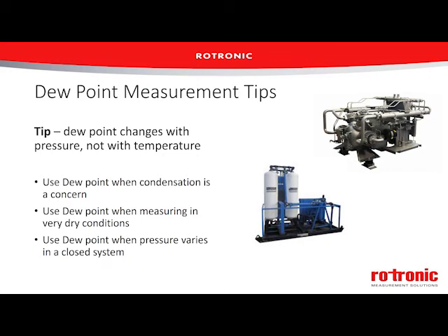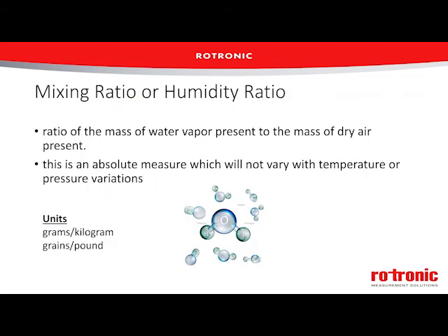Very often we see it being used in very dry conditions, and this is where the difference between dew point and frost point is important, because at those very dry conditions, quite often we're actually reporting a frost point. And we always need to be careful when the pressure changes. That is one of the key concerns: pressure changes will affect our measurements. And with that, I'll pass it over to Bruce to go through mixing ratio.